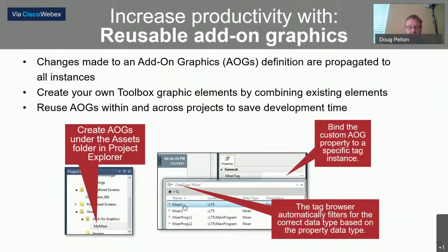When it's closed, it's red. And that's great for the process industry. However, if you took that same valve and wanted to use it, let's say, for a utility, a wastewater plant, they generally want it to be the other way. They want their valve to be green when it's closed. They look at that as a safe state, and red when it's open, and then on transition, they want it to be yellow. So you can go ahead and change that right in the add-on graphic and not have to rebuild that.